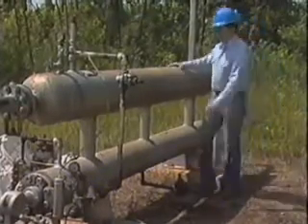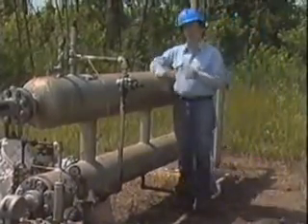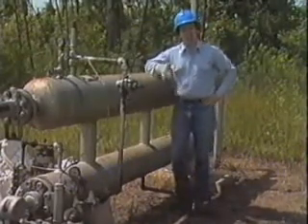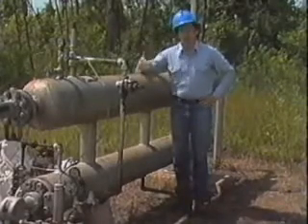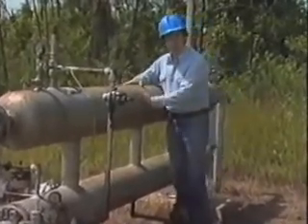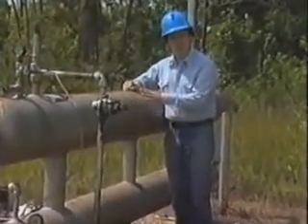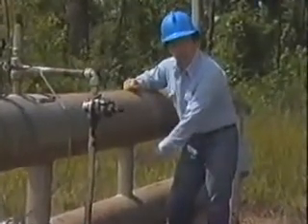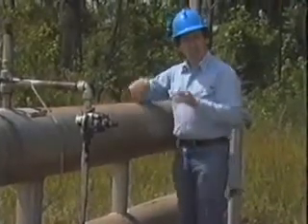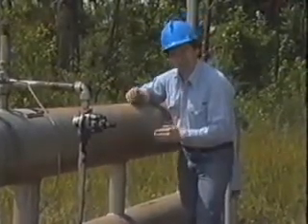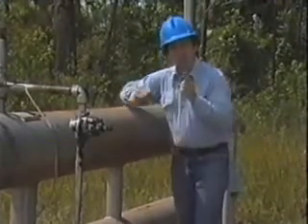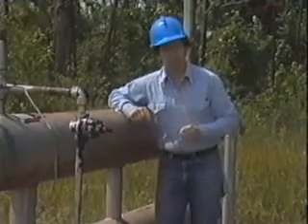Well, as you can see, we've added another horizontal cylinder. This gives us added separation required by applications where the well stream surges often. The upper tube houses the gas separation section, and the lower tube houses the liquid accumulation section. The 2 cylinders are connected through vertical pipes called downcomers. This separation minimizes the risk of re-entrainment.